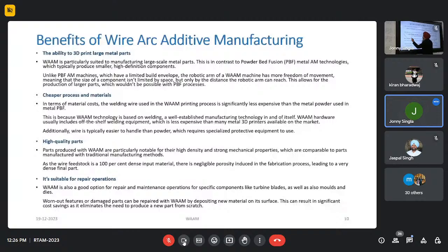Let us say something is going wrong at this portion, which time and again wears out. So that is the cause of concern. So I can think of having a strategy in place where I can repair this blade with a superior material also. For example, this is 316L grade. I can think of opting for some superalloy like Inconel here, whose corrosion resistance and wear resistance would be relatively high as compared to that of 316L.